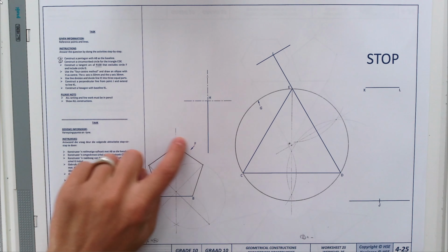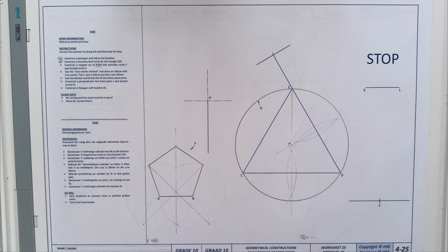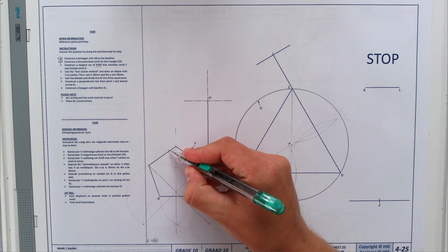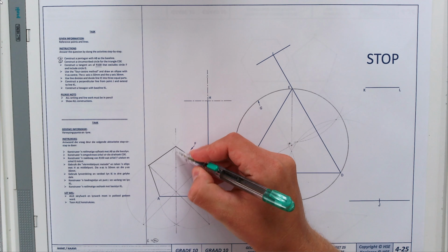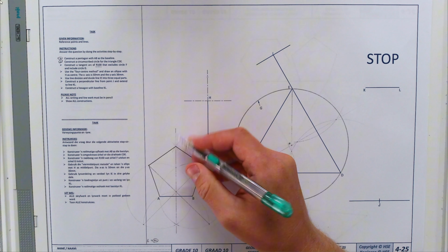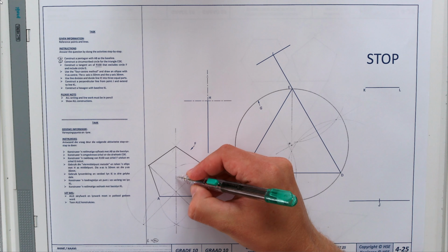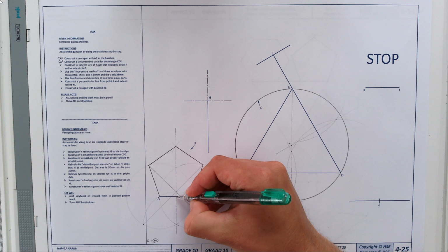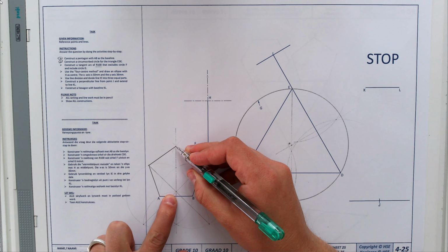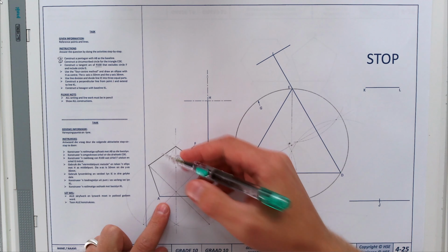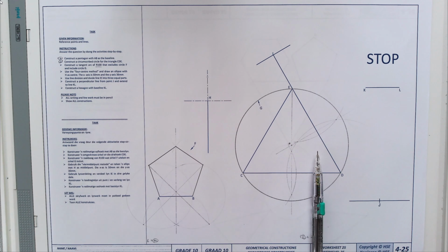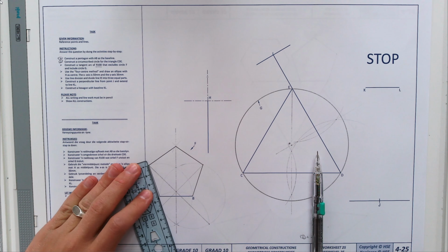So in order to get a circle here at this pentagon, we need to get the middle point of the pentagon first. You can see here that this corner has been bisected in the middle. If you follow this line, it goes to the middle point of line AB. So in the middle of AB, there's a line that goes to the opposite corner. We can do the same here. What is the length of line AB? 35.